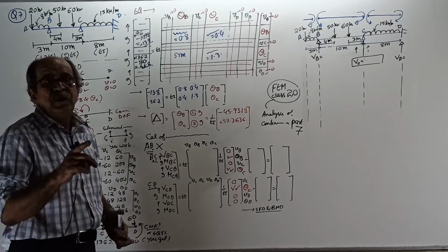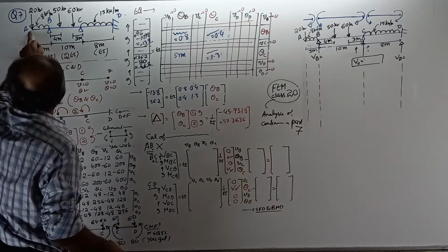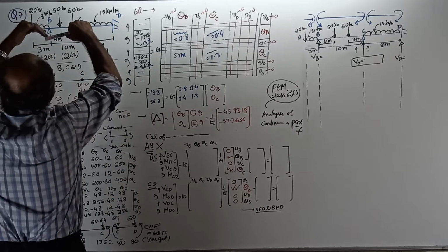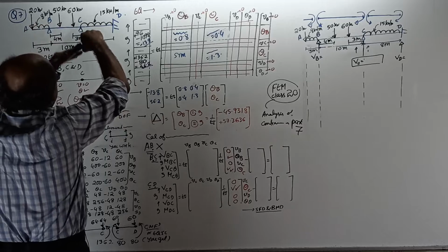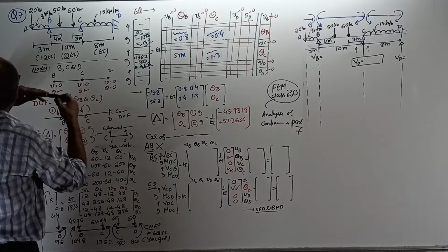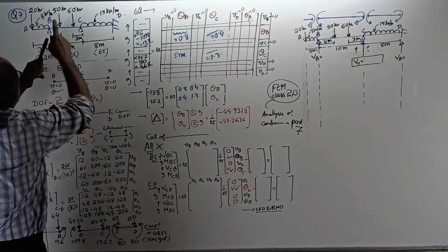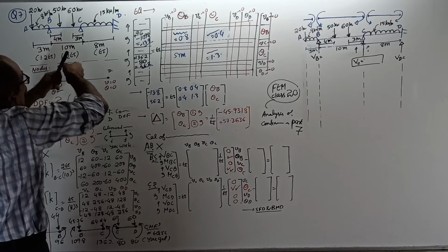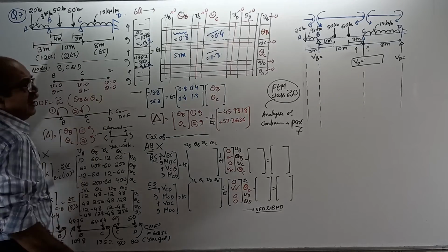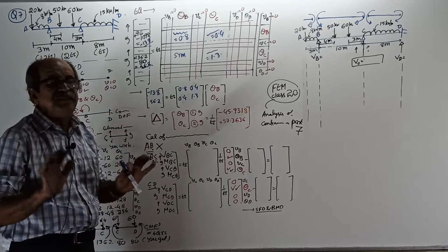Now, when you find the equivalent joint load or consider nodal forces for member AB, the cantilever, see here, when you consider 20 down and 8 into 3 down, it will have an upward reaction of 20 plus 8 into 3. And it will create an anti-clockwise moment about B. So that will give a clockwise moment. Because it is clockwise, you got anti-clockwise here. Already explained. There is a limit for explaining everything.